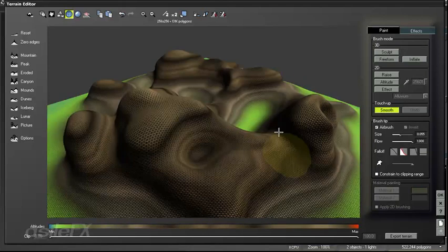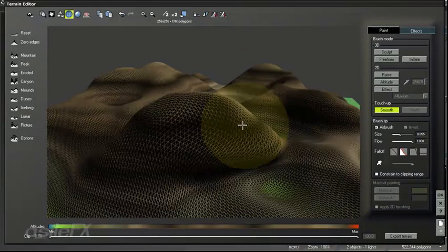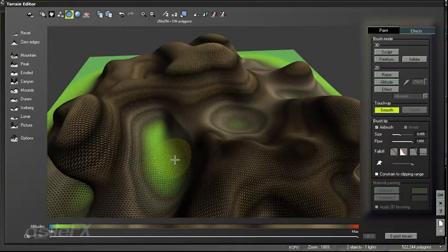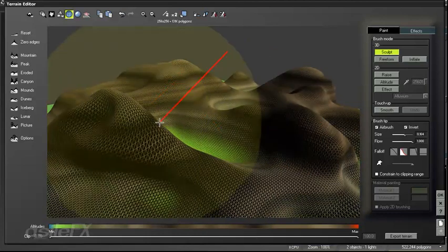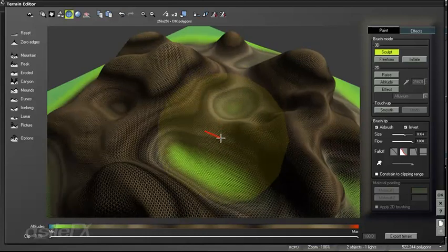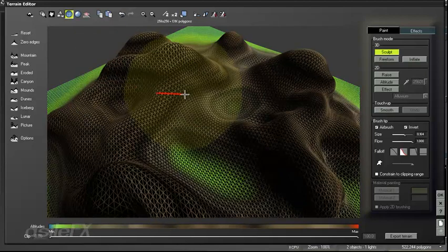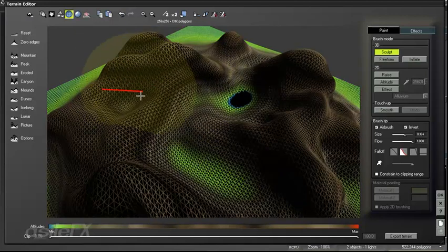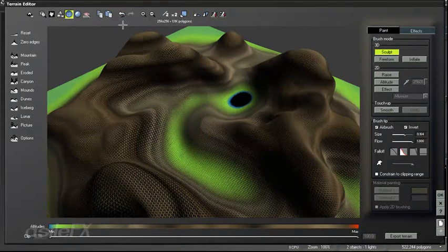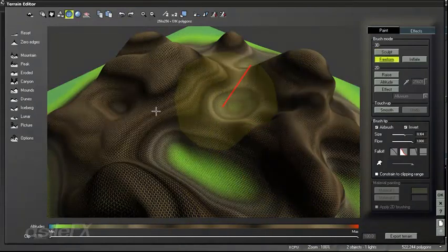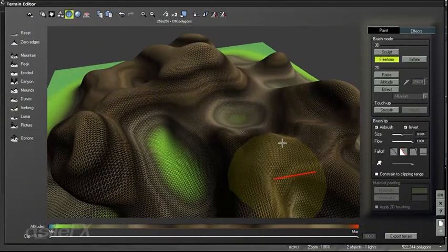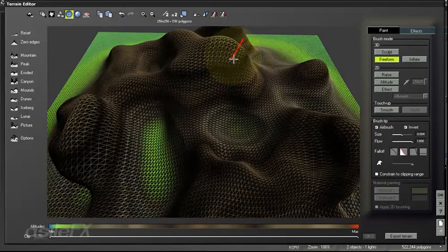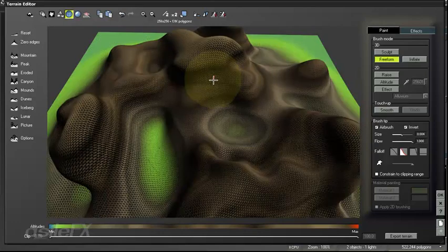So I'm still going through and improving this. Another thing you'll want to avoid is excessive usage of the sculpting brush while traveling across large amounts of the terrain. The reason for this is that since the normal direction stays exactly the same, it will end up stretching polygons possibly too much and creating a fairly uneven mesh. So it is probably going to be best just to stick with the freeform tool. Not that I'm saying you can't use the sculpt brush, just really pay attention to how you're using it.